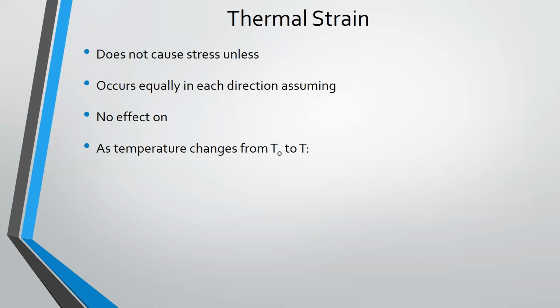Okay, so temperature causes strains, but it does not cause stress unless something very specific happens. So if I have an object just sitting here, and I heat it up real hot, it's going to expand. But there won't be any stresses associated with that.